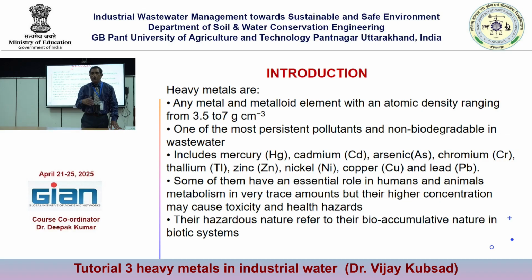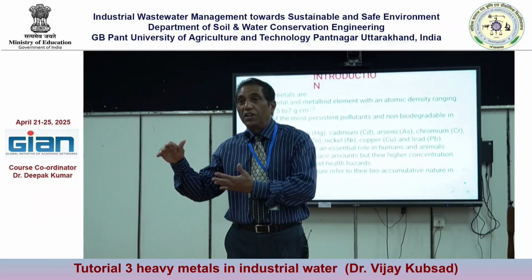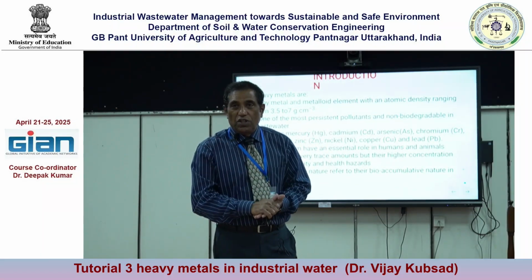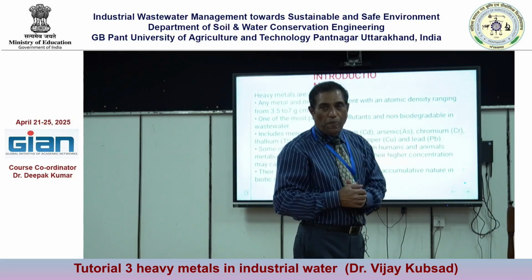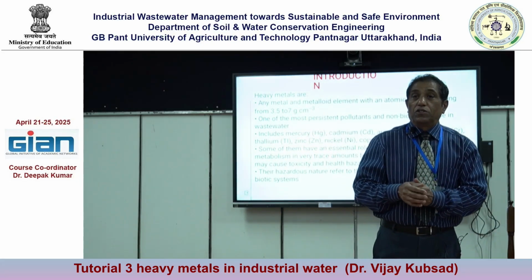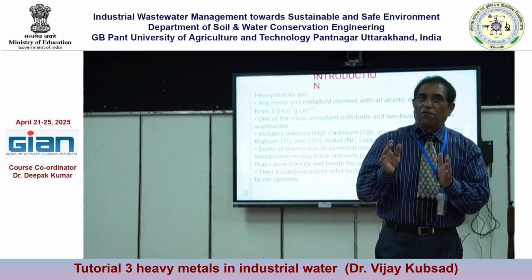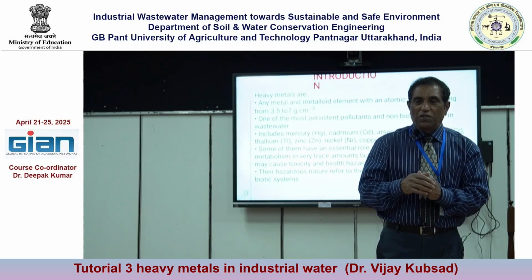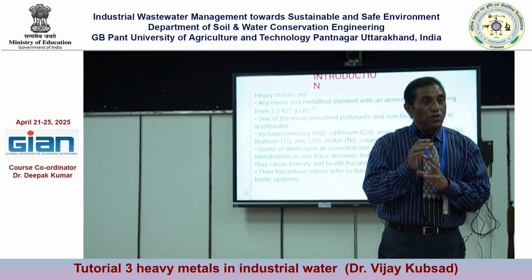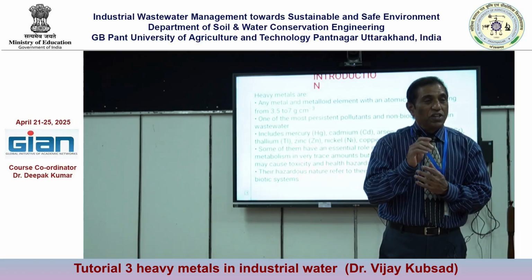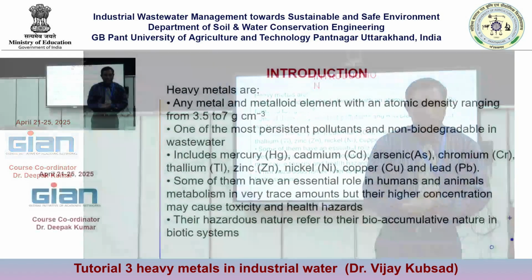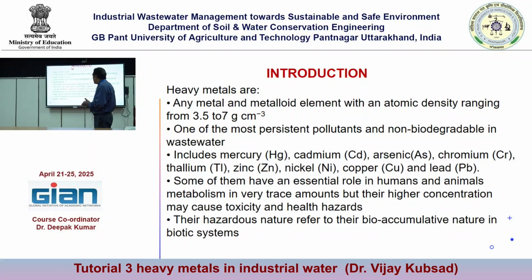You have a method. How you will find out BOD? You do the analysis, you will take the sample, put that and seeds, and then you keep it for 5 days and you see the degradation of organic matter. You know the initial concentration. You will find out. But COD, you have a COD reflexer. There is a method where chemically you want to know how much is COD. Chemically, it can be degradable, right? So that is how it is.